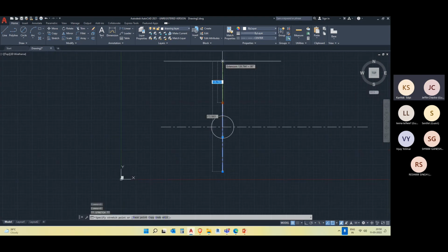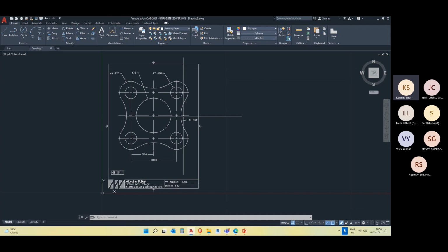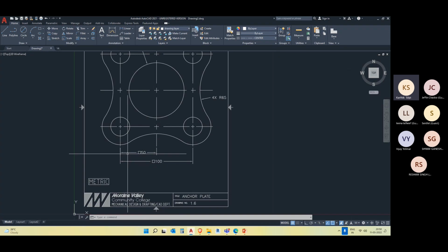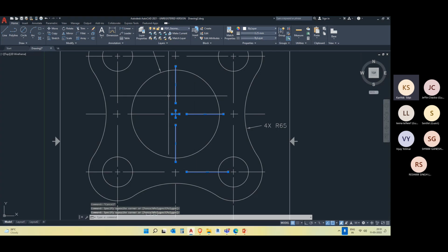Why am I drawing this? It's for my reference. Even in this drawing, whatever they have given, they don't have any dimension for these lines because these are reference lines. The only thing that matters is that it should be presentable. If I extend this line to here, the drawing will consume more space. The drawing should be in this block only. So we have restricted this line to this much. These lines don't have any dimension. Only the areas that we have given dimension. This dimension is given only for the measurement of this inner circle's dia to this outer circle's dia. And this dimension is the inner circle's dia between two ends. That's it. There is no meaning or function for these lines except for reference. That is why we denote them in dotted lines or dash-dot lines.